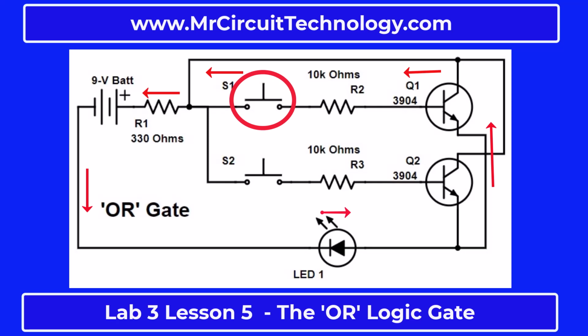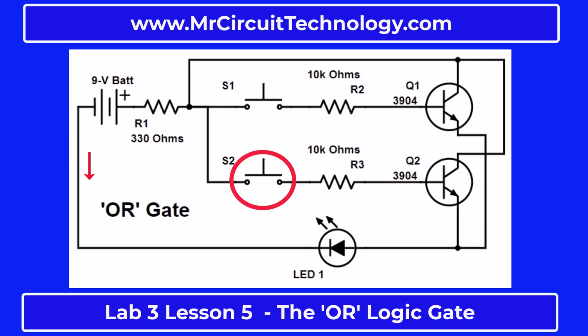When you press switch S2, the current will flow from the negative of the battery through the LED and then through transistor Q2 through resistor R1 to the positive of the battery. When both switches are pressed simultaneously, the path for the current is from the negative of the battery through the LED, then through transistors Q2 and Q1, then through resistor R1 and back to the positive of the battery.